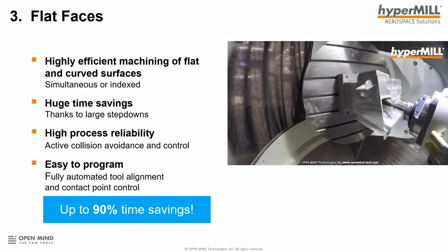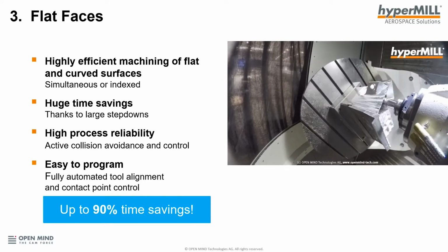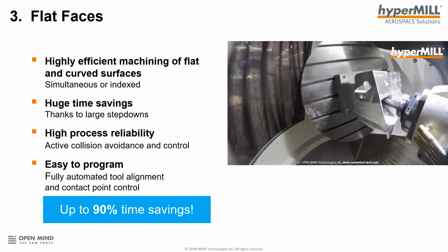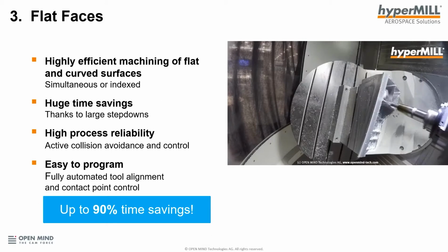So if the pocket is deep, and I think this pocket is something like 160 millimeters deep with a 4 millimeter radius, then the tool needed, if you were going to do it conventionally in a 3-axis approach or a swarf cutting approach, means a very long tool with a very small radius, which is like the dream fantasy tool that you can program in a CAM system, but in reality would never work in machining.